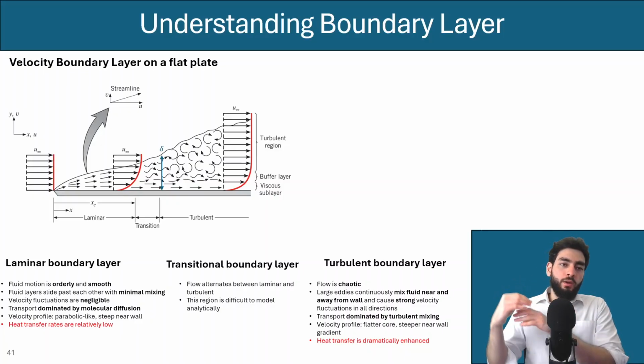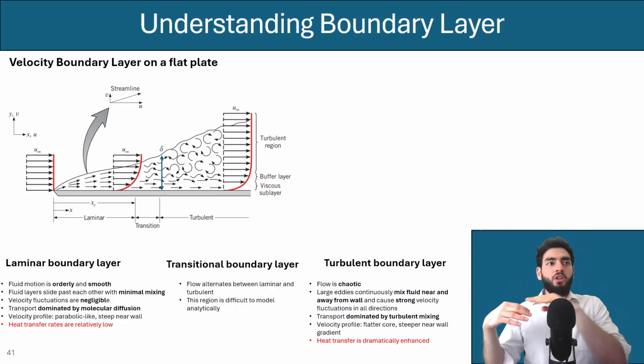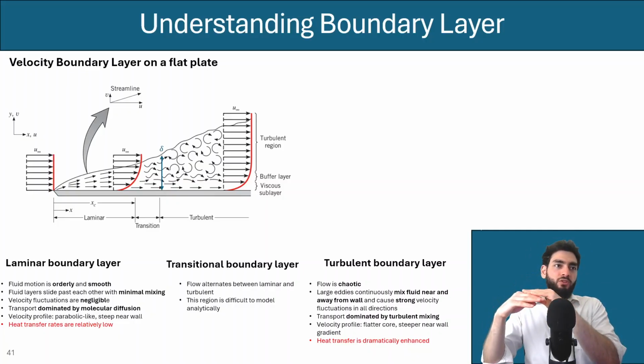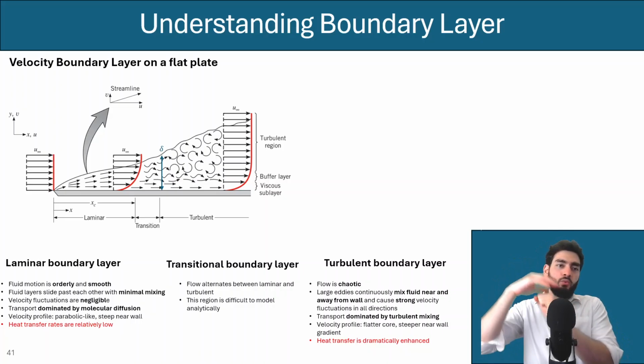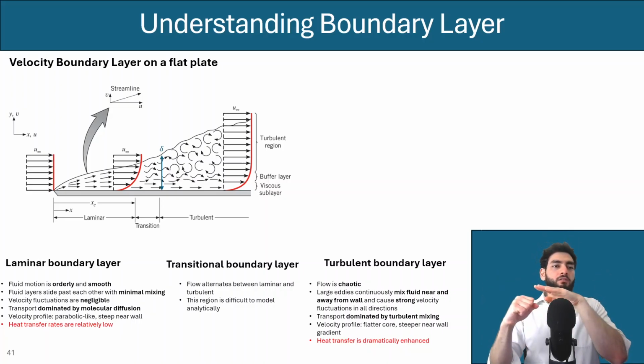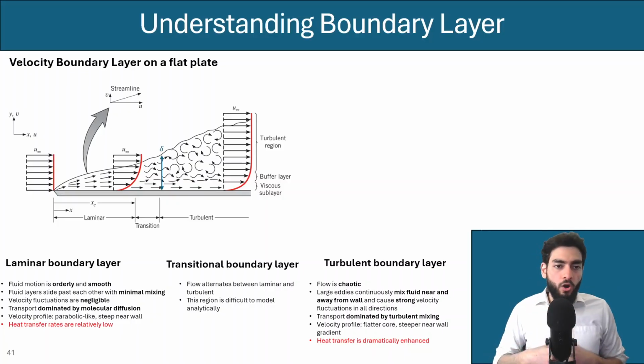And so when you have a lower velocity molecule, let's say closer to the wall, that collides with a faster, higher velocity molecule that's farther away from the wall, what happens is a net exchange in momentum, and that's how you have molecular diffusion in this region, and that's how the influence of the wall spreads in the y direction.